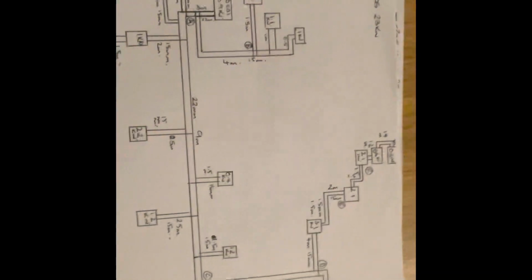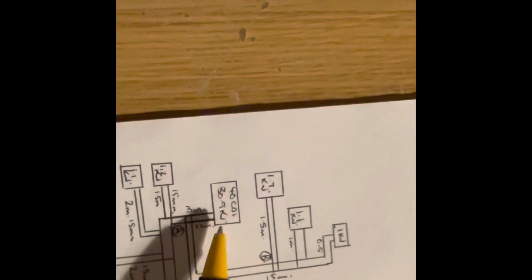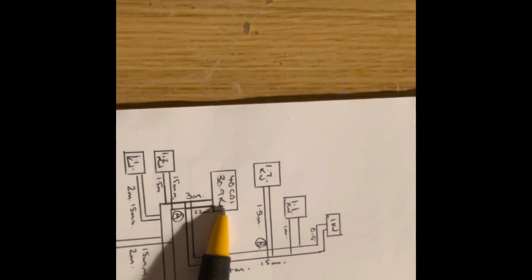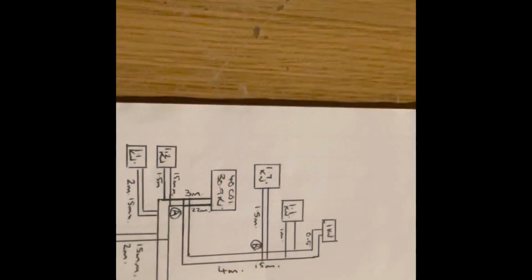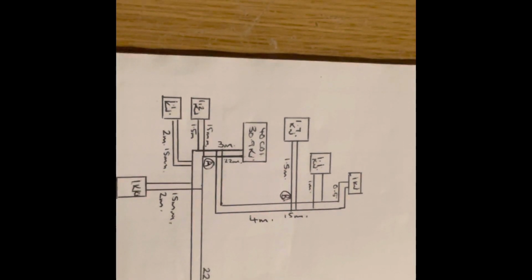It's not actually about that, it's about how much water you can transfer down these pipes to get that heat requirement. As the heat exchanger becomes bigger inside a boiler, it becomes deeper and adds a greater restriction to the pump. So this is where you need to start understanding pump curves and working out pressure losses across pipe work. I think if I remember rightly, I've lost the actual chart.